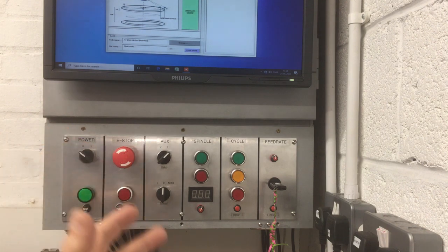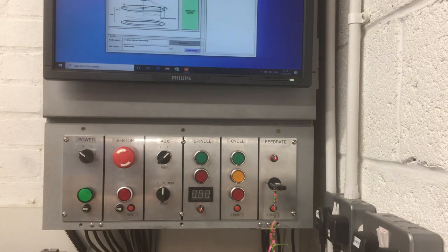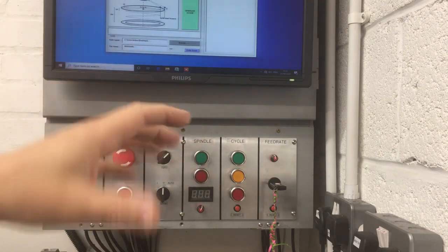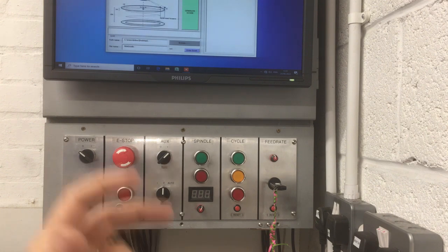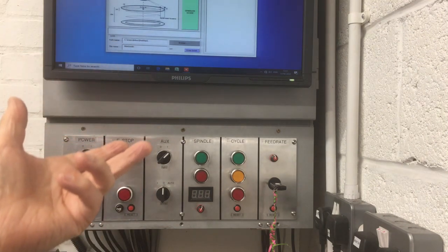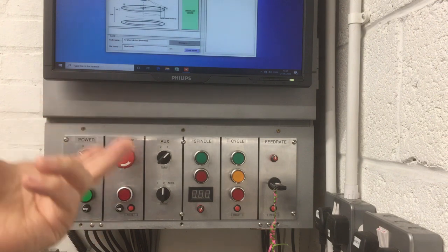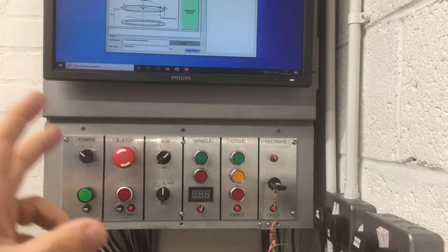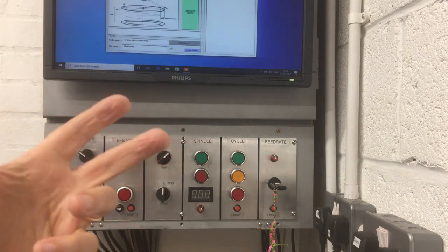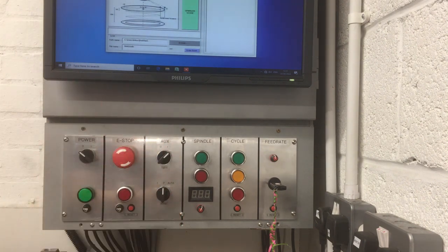Obviously it is beta code. I've only done very limited testing here. It's worth doing an air cut, so just put the tool above the work, zero it up there, and then just cut in mid-air and make sure it's going to do what you want it to do. Especially because I've got no way of understanding what controller you've got and whether your controller is going to interpret this G-code in quite the same way. So just build up your confidence with it before you start to use it for anything on any serious projects, and just take care with it.